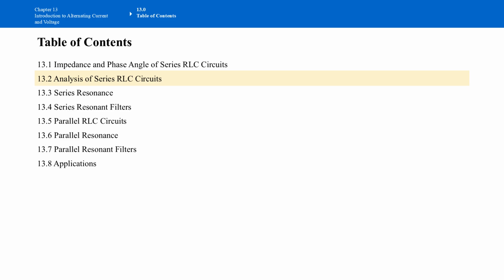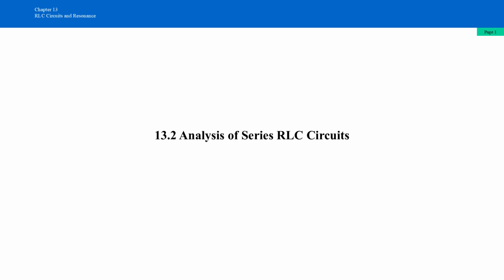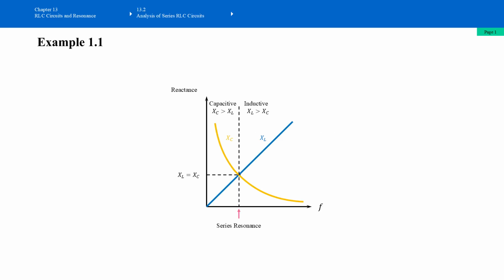This is session 13.2, Analysis of Series RLC Circuits. The first figure we see here shows the relationship between capacitor and inductor, especially their reactance when frequency changes. The yellow waveform shows the capacitive reactance, and the blue waveform shows the inductive reactance.